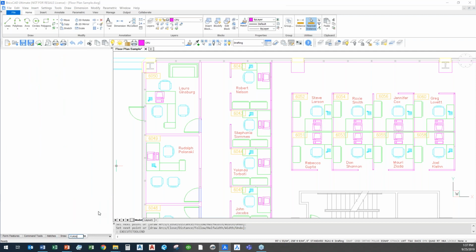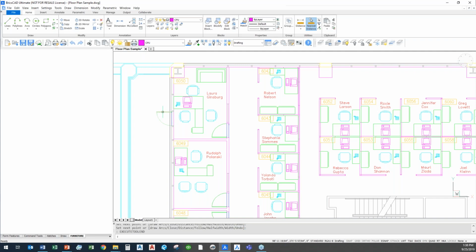And just like I did in my little example there, because I've done that before, I'm going to create one called furniture. And you see, just like that, I've got a tab. So I had draw, now I have a furniture tab down here on the bottom. All right, well, that's easy enough, but how do I get all of these items here into this tool palette?